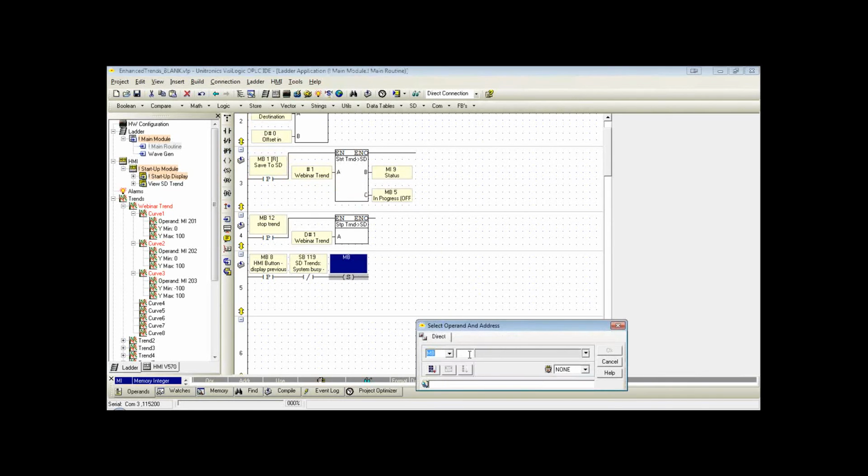And then I will set system bit 118, jump to previous segment. Note, I am setting it here. The OS is going to reset it for me as soon as it completes, so I don't have to worry about resetting it.